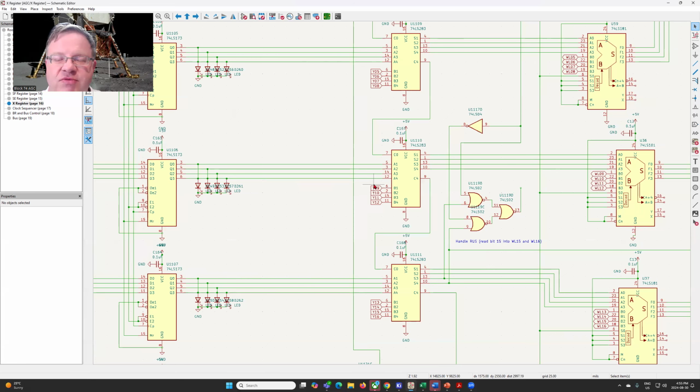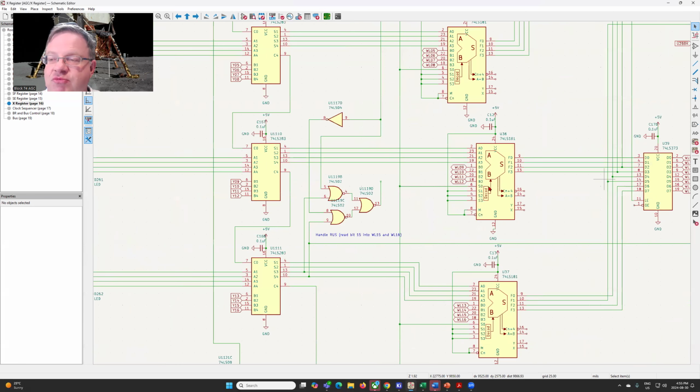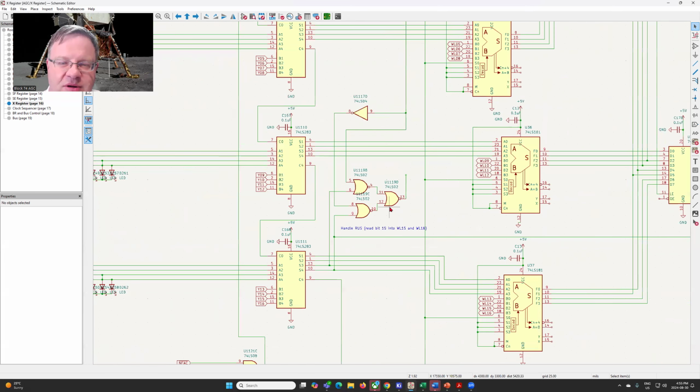Anyway, I'll have a new video out in the next week where we'll wrap up the X register and how it reads and ORs the data back out onto the bus. There are a few variants: there's an RU, which reads out the sum, and then there's an RUS, which does a few other different things. And then there are also some mechanisms to write the contents of the adder, the sum register, into aspects of the fixed bank and the extended bank for memory storage. So we'll start talking a little bit about how memory is arranged within the Apollo guidance computer in the next episode.